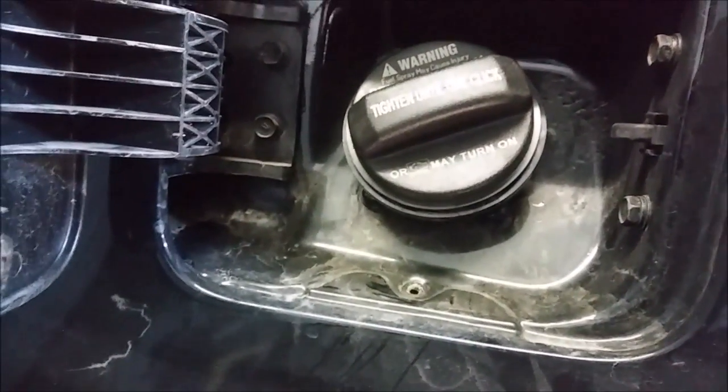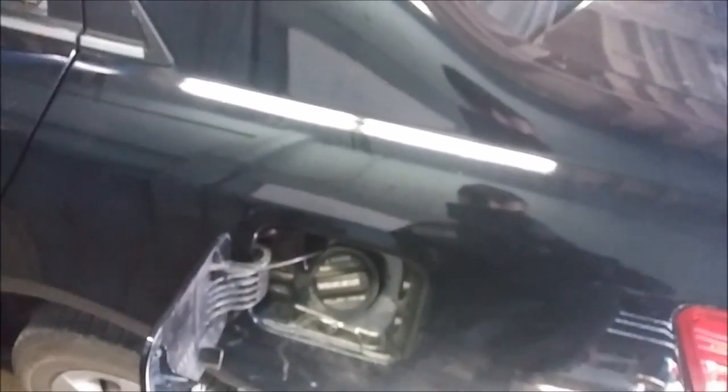So the next thing I want to check, and I've got the vehicle on a hoist here, is the most suspect location for these sorts of things, and that's going to be the fuel cap. So I've just got this fuel door open at this point, and we're looking at this cap. I don't believe there's going to be an issue with the cap on this one, guys, just because it was replaced. But one thing I need to do is ensure that I am getting smoke into the system. So I'm just going to pull this cap off, and I'm going to take a look in this hole.